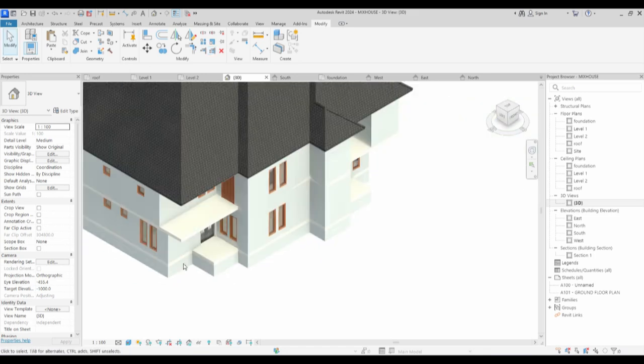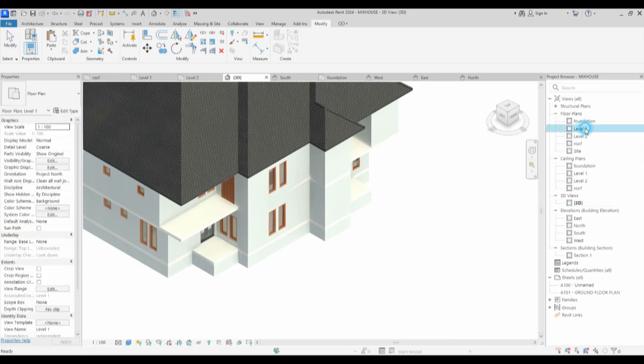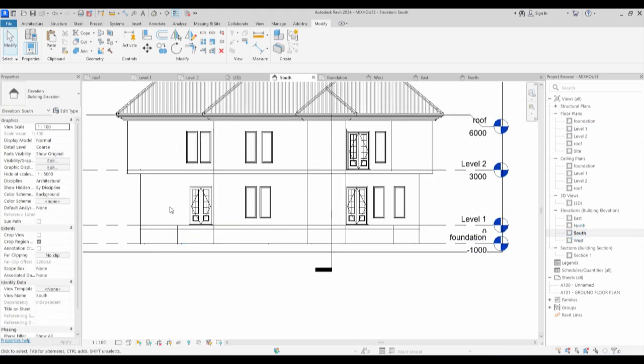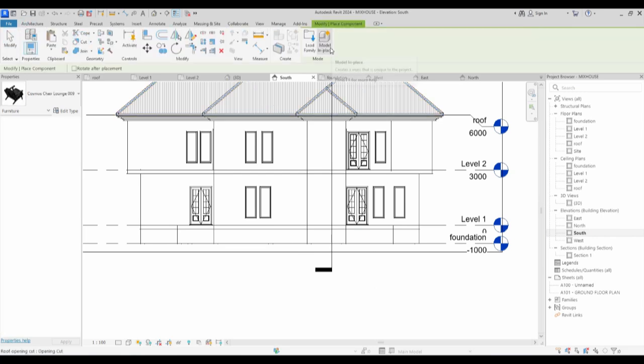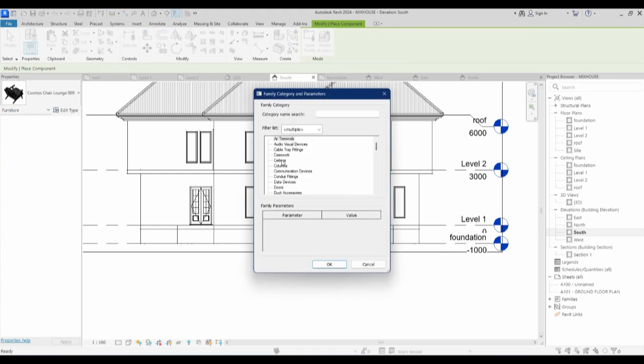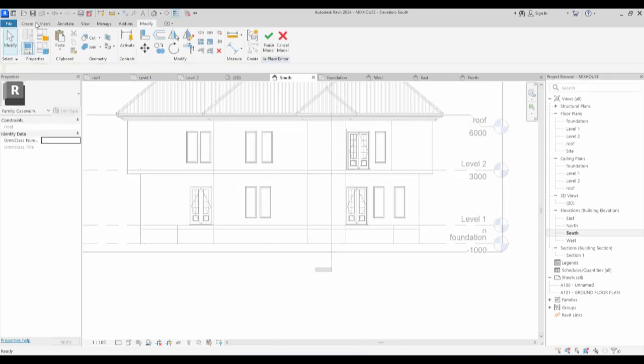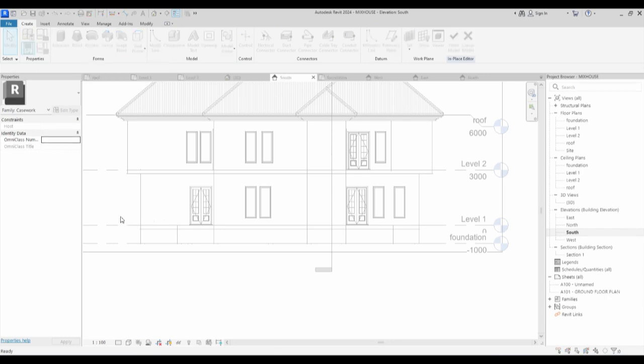So what we need now is to quickly create the stair for this. Go to level 1. From level 1, where we have this, go to start elevation, because I want to create the steps of this one first. I'm going to say component, then model in place. I just want to use casework and I call it steps. There are steps there too, but I cannot be going up and down because of that. So click this one and say extrusion is what I'm going to use.